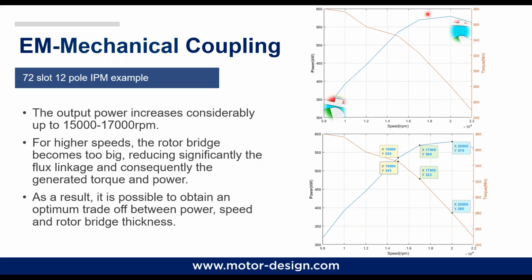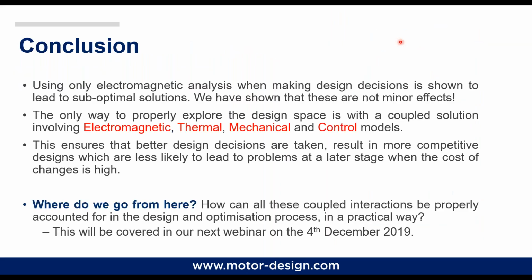So that's why the whole thing comes together. And that's why, for example, in this case, I wanted to show you why electromagnetic, thermal, and mechanical coupling, and the control, must be performed since the early stage of the design process. So what we have shown today is that using the electromagnetic analysis alone for making design decisions tends to lead to suboptimal solutions, or solutions that may result in problems at a later stage of the design process.